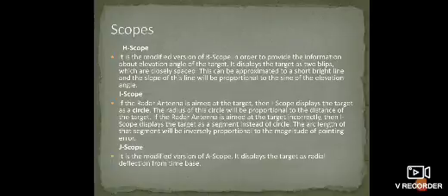It is a modified version of the B scope in order to provide some information about the elevation angle of the target, which displays the target as two bleeps that are closely spaced. A short bright line is seen, and the slope of the line is proportional to the sine of the elevation angle. That is, the H scope is mainly used to get the elevation angle of the target.